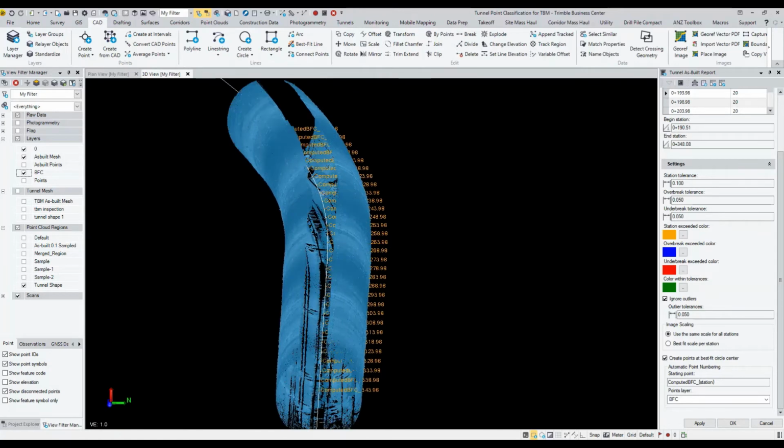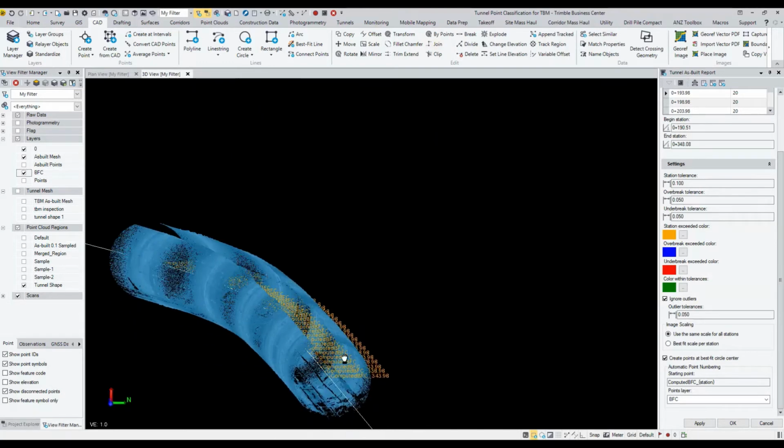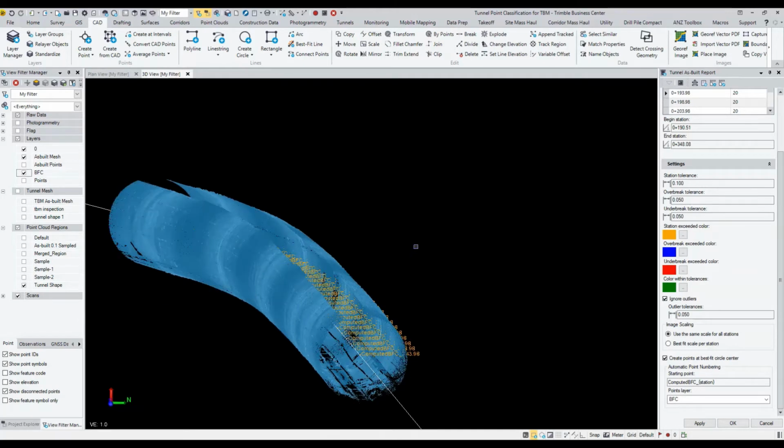Just be sure to create separate segments for straight versus arced, or those curved sections of your tunnel. And then you can use the join tool over here in order to join those segments afterwards and compare those two alignments. Use them for whatever you might be doing down the line, whether that's using those updated alignments for installation of different features to come later, electrical, plumbing, different things like that.